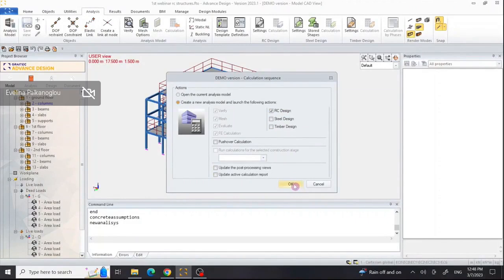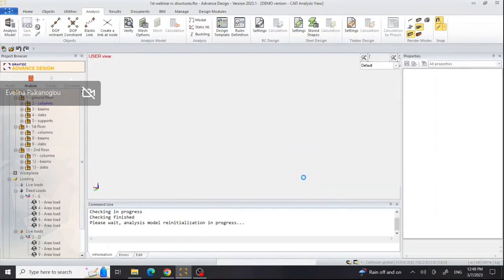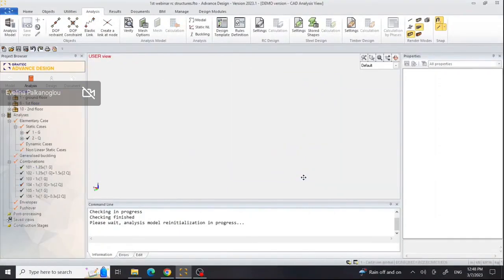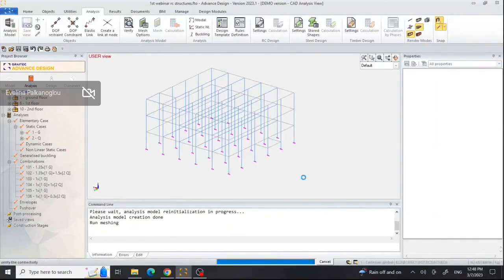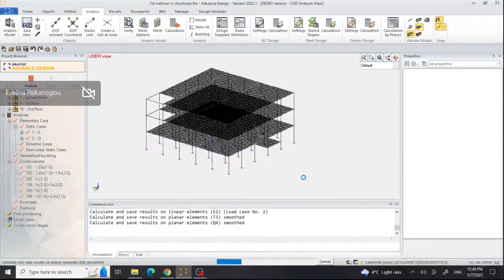The reinforced concrete design pretty much does the finite element calculation again, so that's why you see those areas selected. And normally the reinforced concrete design is affected by the number of elements used or the mesh options. Normally, it doesn't take too long, as you will see. You can access your results quite easily and effectively, and quite quickly, I would say.